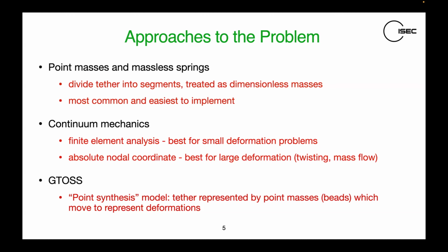And because we're going to have deformation problems and have to predict those and solve those, small deformation systems like finite element analysis may not be sufficient. We would probably have to go to something like absolute nodal coordinates. And this is good for large deformations, so we may have to deal with twisting and mass flow and things like that.